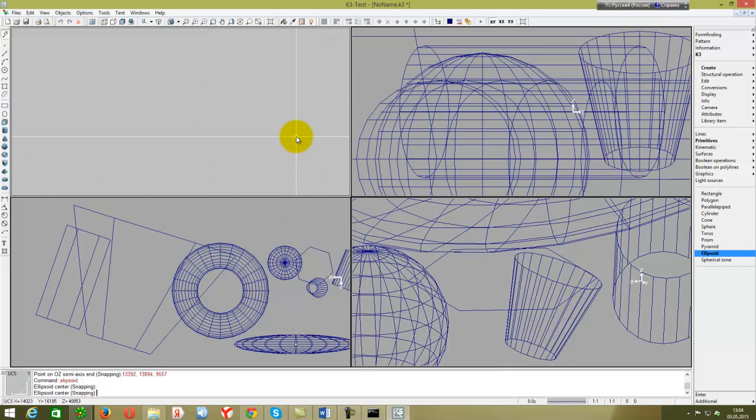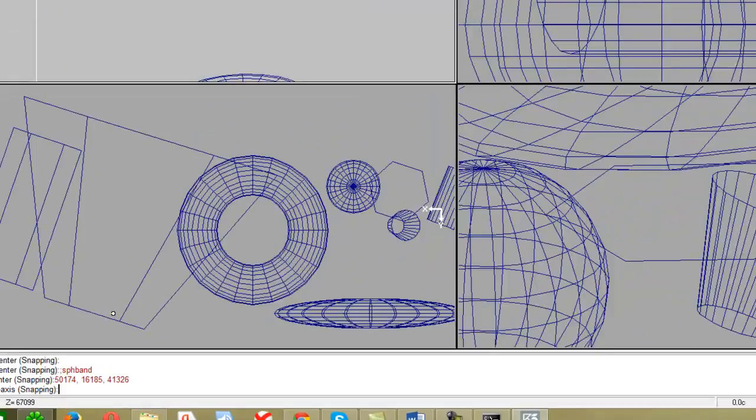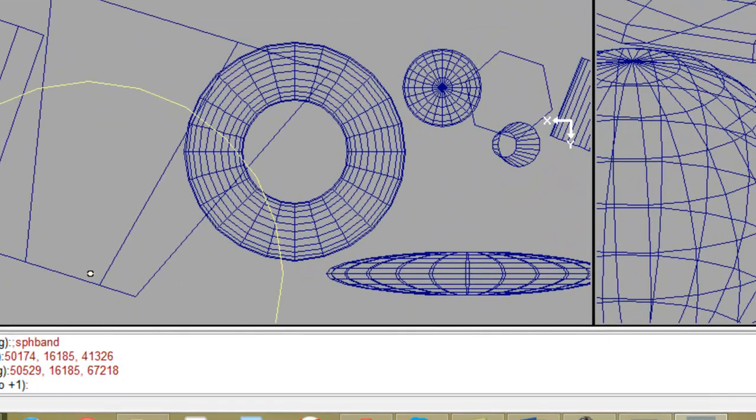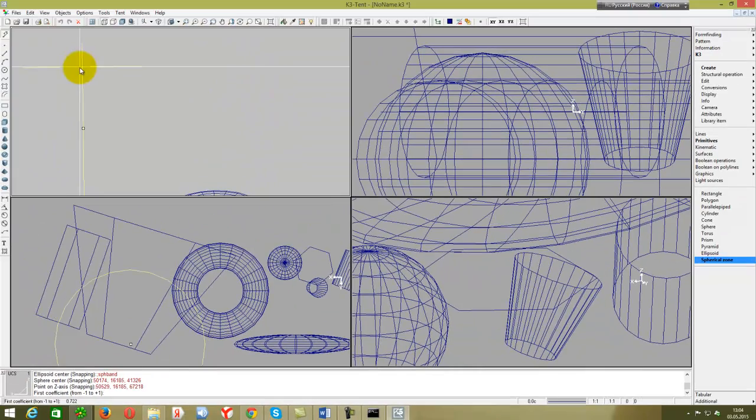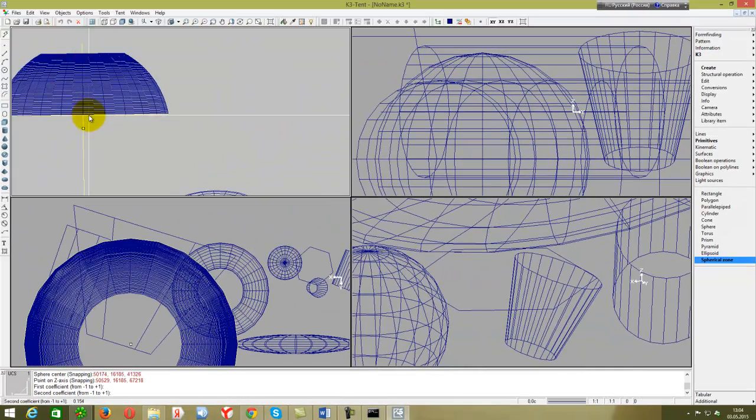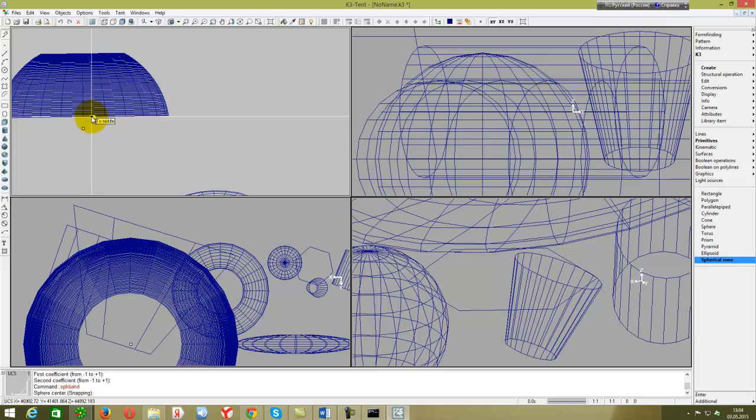To create the spherical zone object, we should define the center of the whole sphere. Then the point at axis Z, and two ratios that can be varied between -1 and 1. These two values can be calculated as ratios of the distances from sphere center to the base points to the radius.